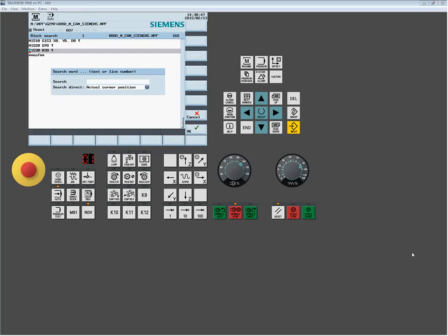But remember, the system is going to vector to the starting point. So make sure you leave it in a safe spot where it's going to go shortest path. It's going to do potentially up to a 3-axis move to get there. So it's pretty common to move her away and then jog her back kind of close before you restart the system, so then that vectored position isn't that great. All right.